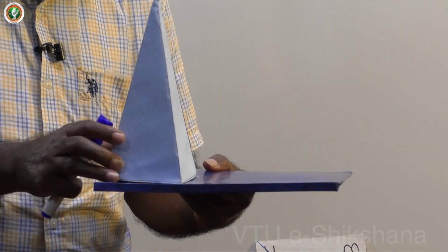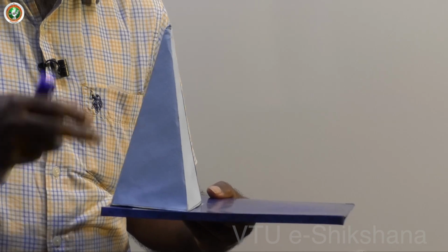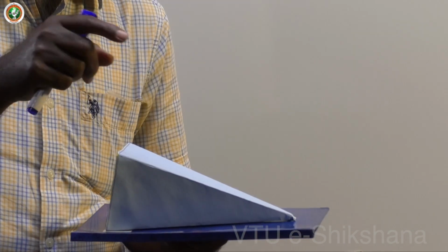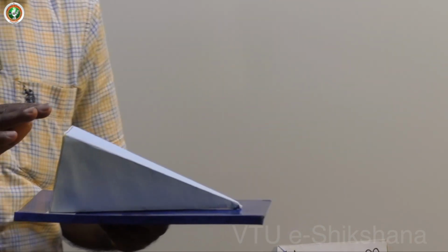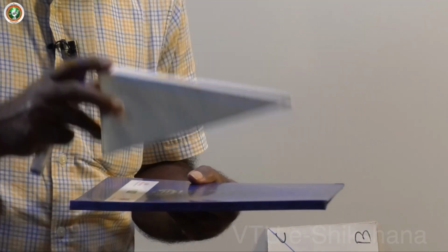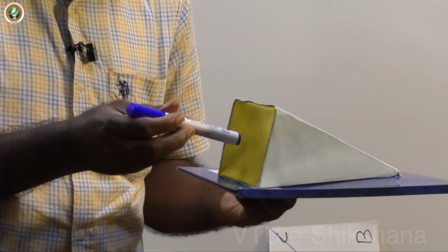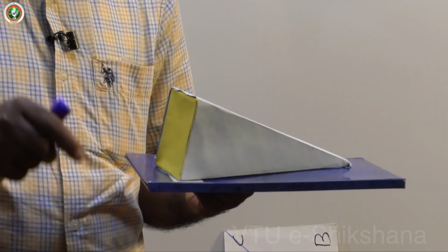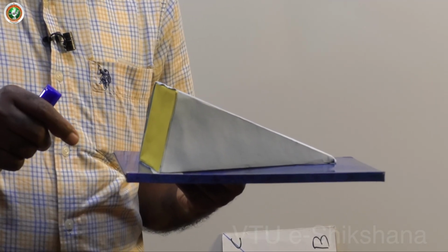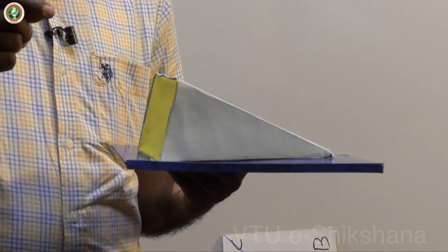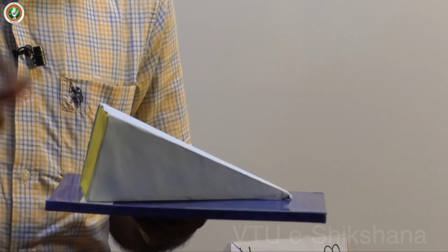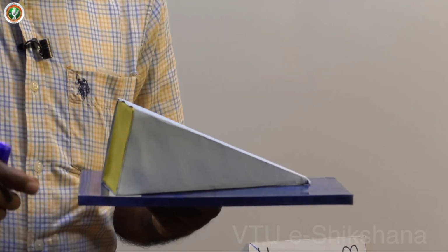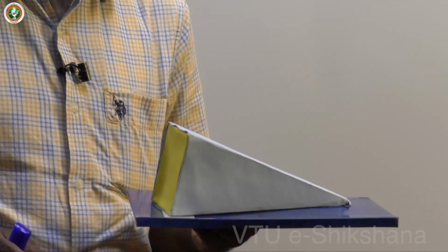In case of the axis, if they give it, take the true angle. Here, the axis is already inclined at some degree to HP, but it is not given. Once the slant face is on HP, definitely the axis assumes some inclination to HP. You have to check the top view of the axis. If the top view of the axis is foreshortened, that is apparent length, then definitely you must consider beta, because of apparent length and apparent inclination.